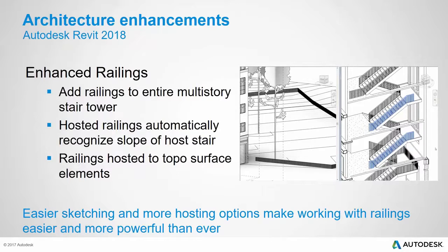So there was a question about the stairs specifically. I said, did it adjust the risers and the treads? It actually did adjust the tread counts, and it did adjust in a minute way the actual riser heights. There's a maximum riser height that Revit can set. On the commercial side, I believe it's like 6.5 inches or 7.5 inches for the riser height default. It will guarantee that it won't go over that, but it will adjust the riser heights automatically as needed to give you the right quantity of treads to go up to the next level. So yes, it does do some of that adjustment.